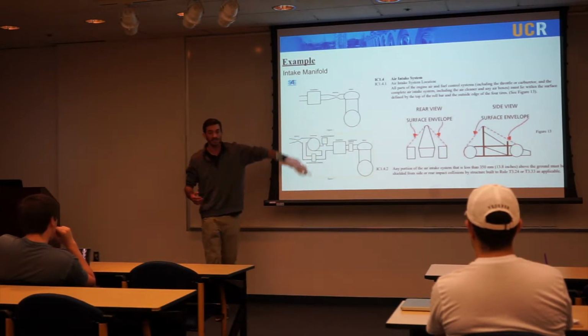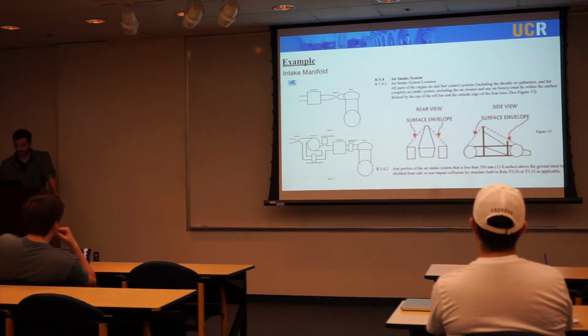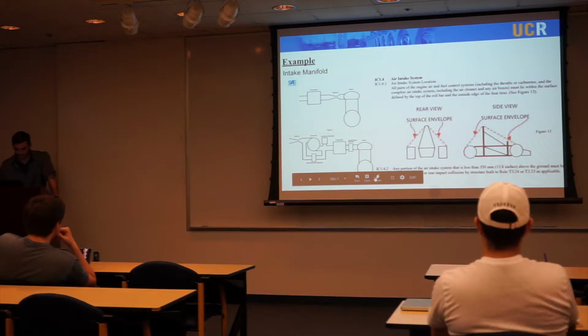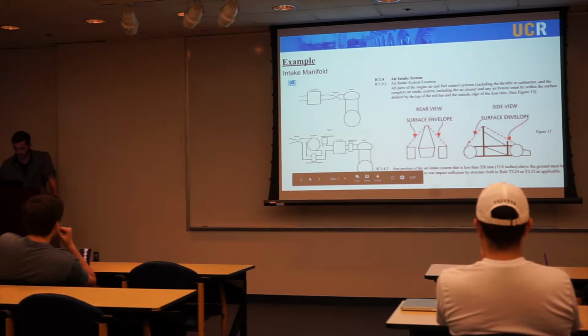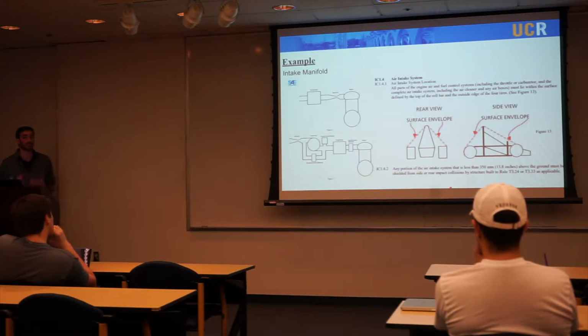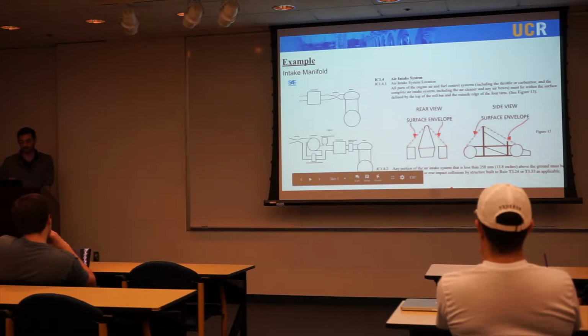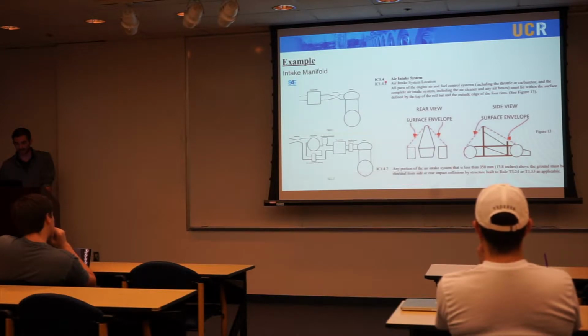The actual size constraints on where it can reach out to define a lot. On our car, you take a horizontal plane from the back of the tire all the way up to the top of the roll bar. Nothing can exit that, right? So that right off the bat is going to limit your size constraints on what you're going to be able to do and what you're not going to be able to do. And if you ever have a question on a rule, you'll format it by taking the rule number here and asking a question. They'll have a drop-down box for that.